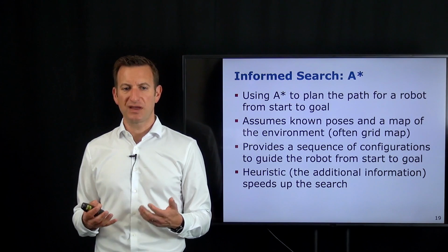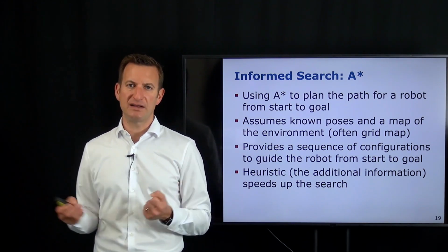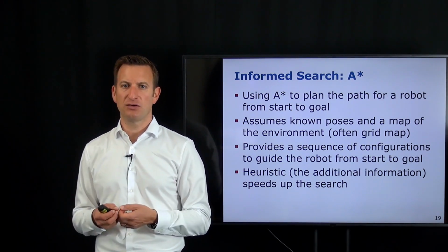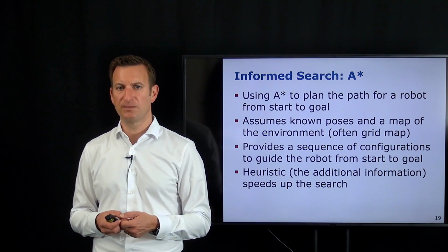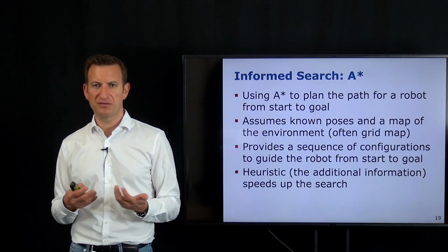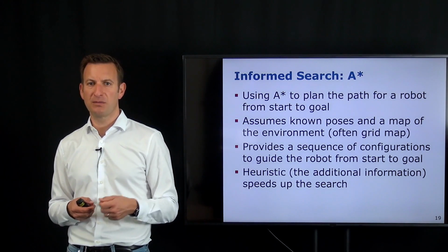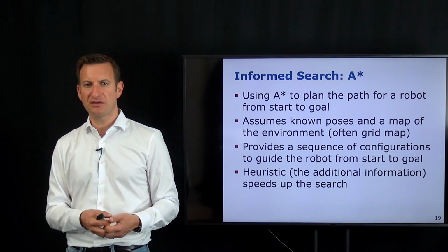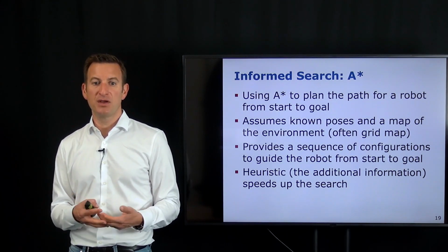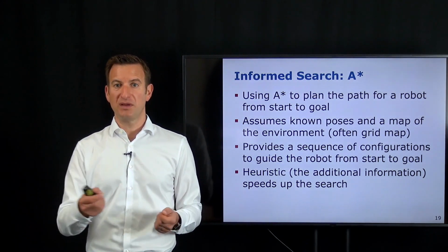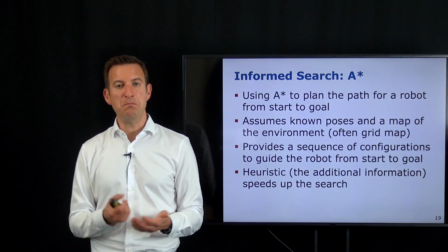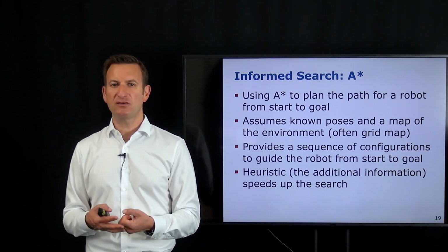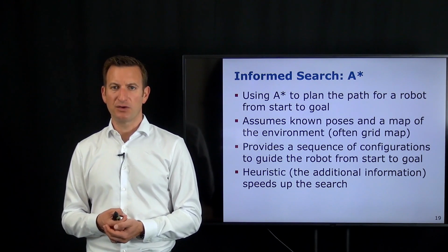Of course, that is something that is not known exactly, but maybe we are able to estimate that cost. So for example, in the Euclidean space, the straight line distance between two coordinates is an approximation of the actual cost or the actual distance between those two nodes. So again, if I'm planning in the space of distances and I want to estimate how far is it from a location, let's say 1, 1 to location 2, 2, and by not knowing how the environment looks like, a good estimate could be square root of 2, because this would be the straight line distance between those 2 points. Maybe the distance is longer if there's an obstacle in between and the system needs to make a detour, but at least I have an estimate on how far those 2 points are away.